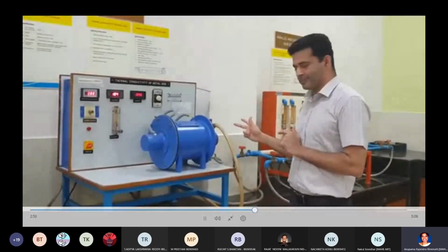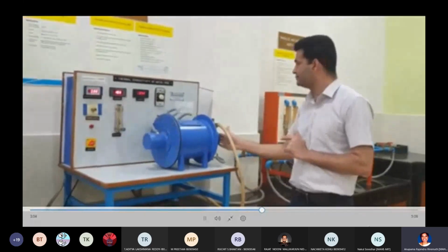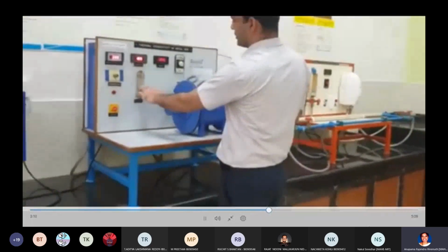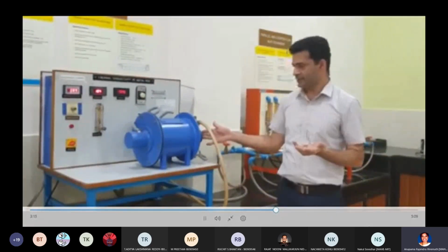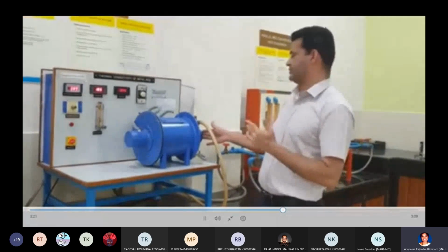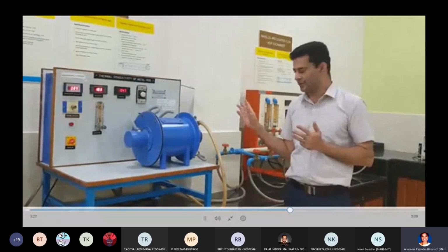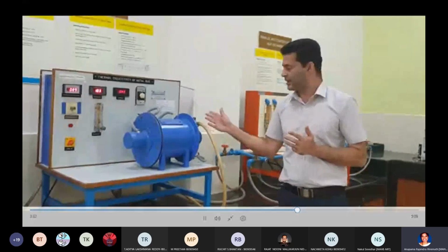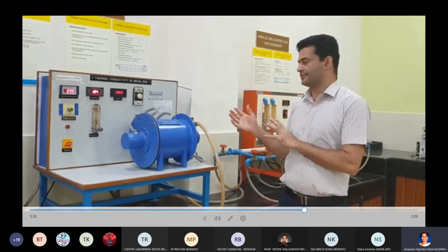We also have 2 more thermocouples to measure the inlet water temperature and exit water temperature in the cooling section. By knowing the mass flow rate of water using the rotameter, and the density of water, we know the mass flow rate. Cp of water we know, so we can obtain the rate of heat taken by the cooling water. So we know the heat conducted to the rod from the inlet and exit temperatures of water, the mass flow rate and Cp.